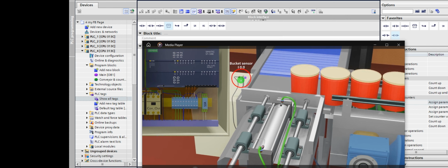This particular proximity sensor has only three cables. Two of the cables are the input signal to get the sensor energized. The other third cable is the cable to activate this relay. And once this relay is energized, this relay has multiple circuits to work with. It can be a 4-circuit relay, 3-circuit relay, depending on your configuration. So the whole of those circuits coming from the relay can energize multiple items and de-energize multiple items.